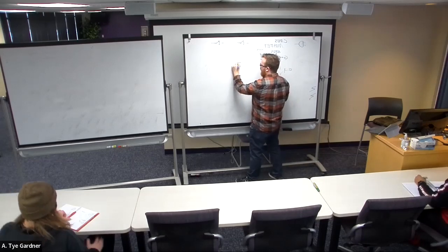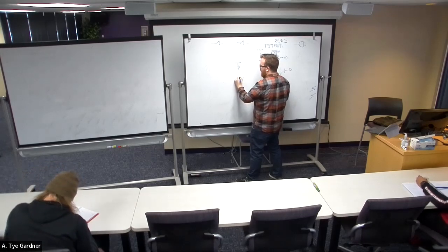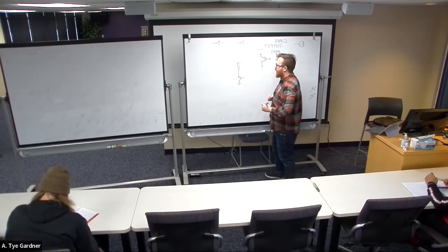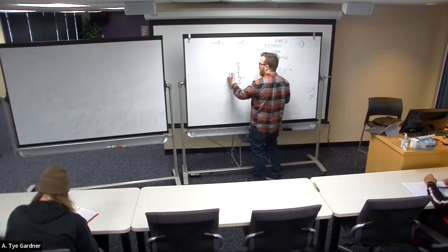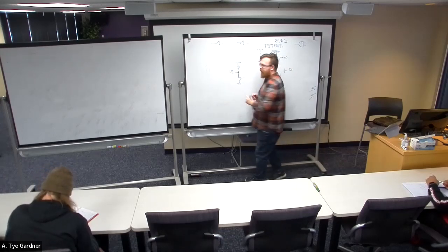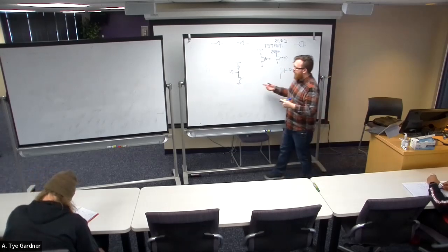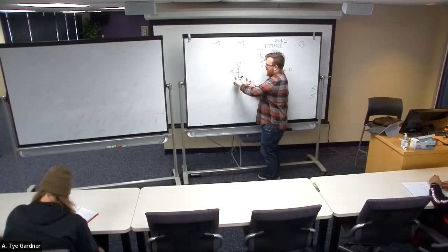So let's say we have the standard circuit that we have, and I just replace the switch with an NMOS device, right? Instead of a switch, I put an NMOS out here. I'm going to call this our digital signal, right? It can make 1s and 0s. Because what happens is if I get a 0 here, then it's disconnected, right?